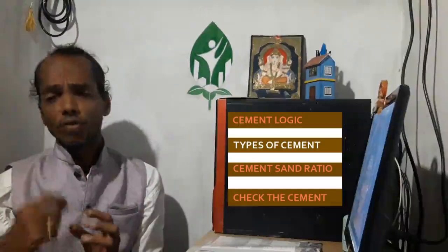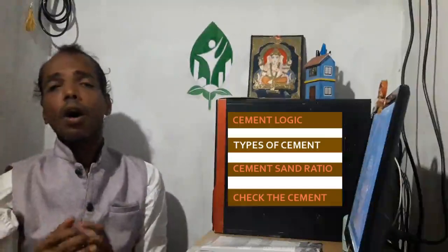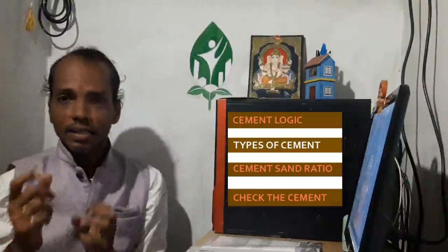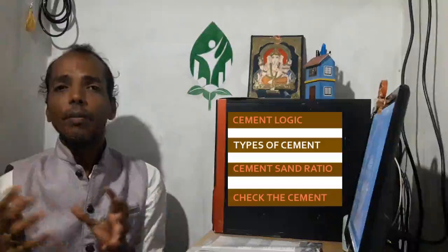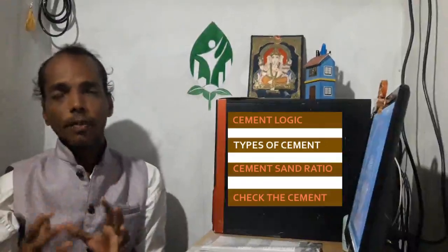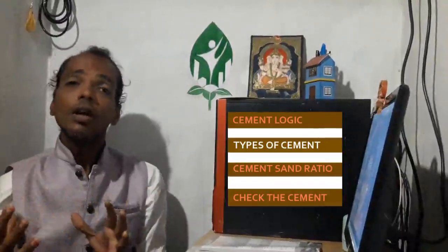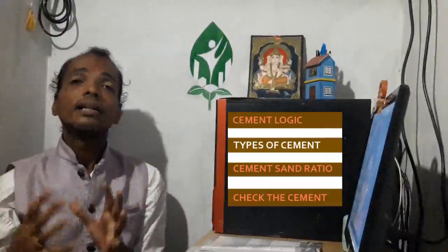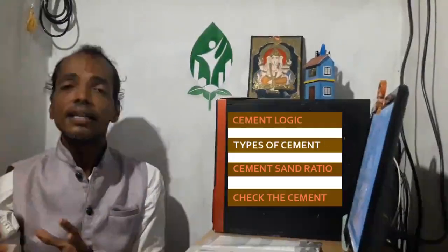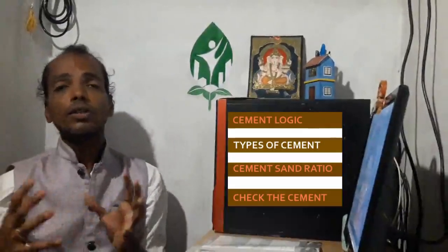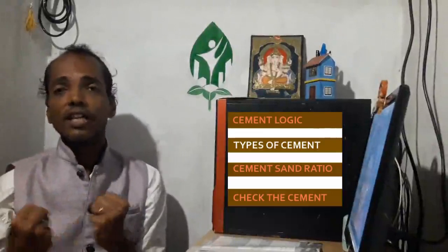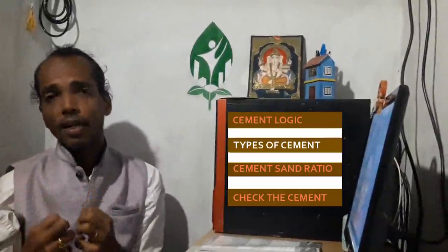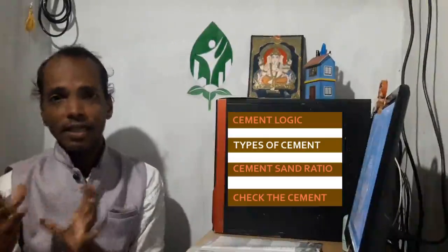And there is one more important cement called Portland slag cement. This Portland slag cement is manufactured with a combination of slags. This particular cement is very useful in the construction of dams and the construction near the seasides, under sea water and all. So this has very good resistance against alkaline reactions and sulfuric reactions and all. So this Portland slag cement is used for dams and seasides.